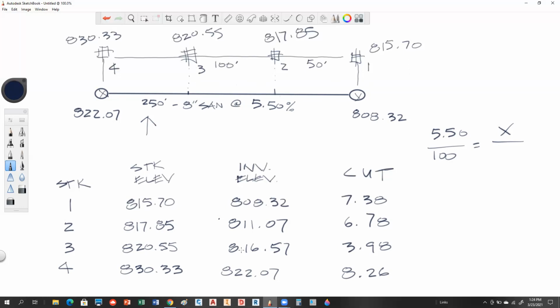Do you know why? Is it cumulative error? Yes, it's cumulative rounding going on. So you're better off going from the longer distance than adding the shorter ones sometimes. It just depends.